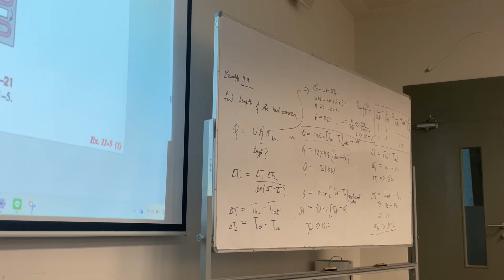So now we have the cross flow. Okay, so you also have to look at the heat exchanger and you should be able to understand what type of heat exchanger it is. This is not counter flow, right? This is not parallel flow. This is clearly shell and tube. Okay, this is a shell and tube heat exchanger. Now shells. Shells are this. If you remember, this is one shell, this is two shell, four tube. 1, 2, 3, 4. Four tube. So that's how you classify.